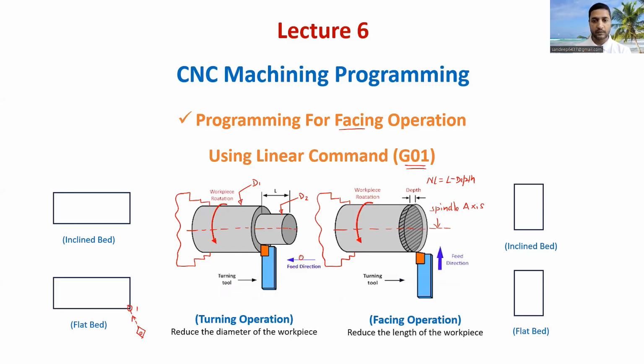This is point number 1. Now we are taking some depth of cut in order to remove this much material from this cylindrical workpiece. Let us say we are reaching point number 2 with the rapid traverse. From point number 1 to 2, we are reaching with rapid traverse, because here you can see there is no contact of the cutting tool with the workpiece. So this is our point number 1 and point number 2, rapid traverse. I am showing you this figure for better understanding. The same example I am showing here also.